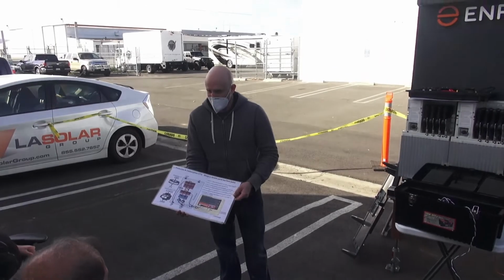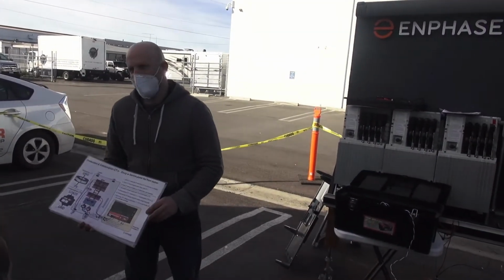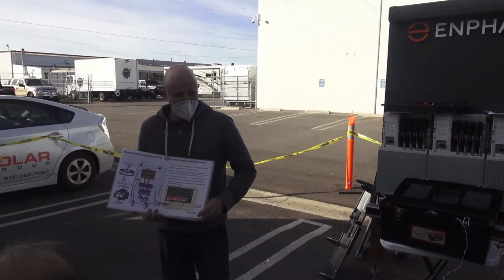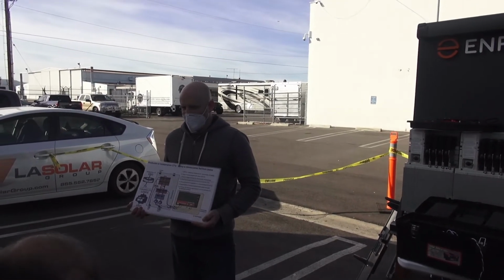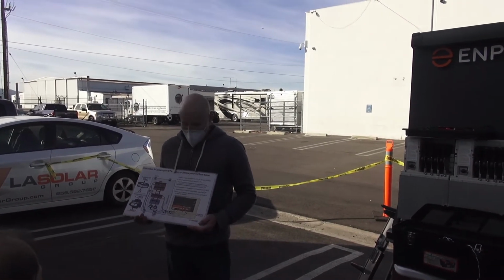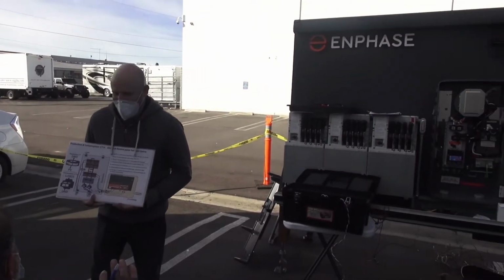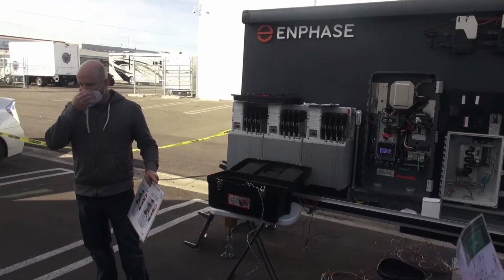Yeah, we do have the same problem with Tesla systems. But it's usually the consumption CTs. Everybody's got 400 amp main panels now, and Tesla only makes CTs in 200, 600, and 800. Nothing in between. Right now, we don't have many options either, so you have my sympathy.